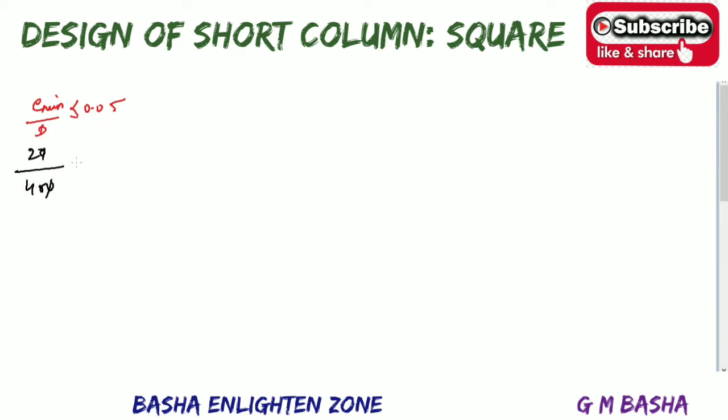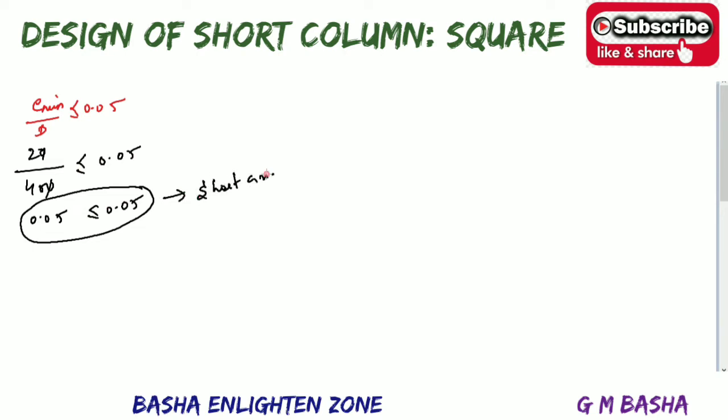Simplify that, how much do you get? You get 0.05, so that is equal to 0.05. So if you get the value e minimum by D less than or equal to 0.05, you can design this column as a short axially loaded column.